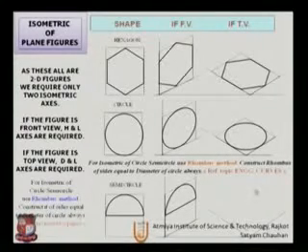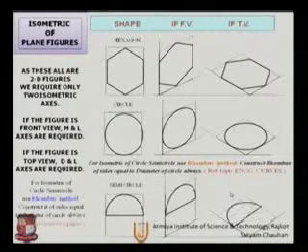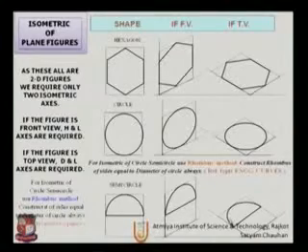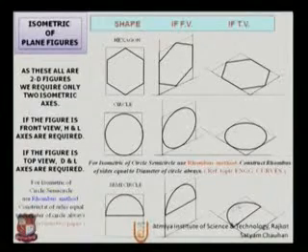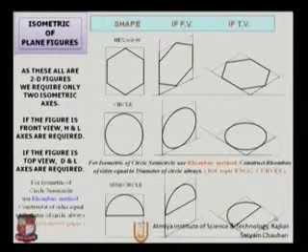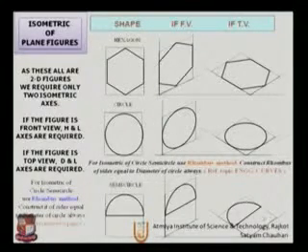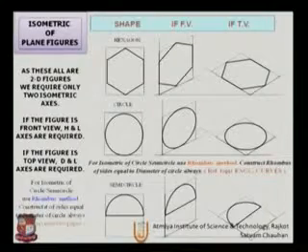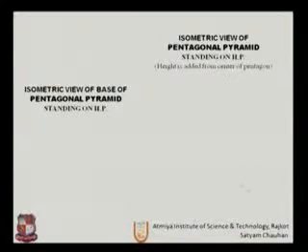To get the top view of the semicircle, repeat the same steps. Draw the rectangle first and then complete the bigger and smaller radius, the bigger from the diagonal points, and the smaller from the base points. So these are the basic shapes.